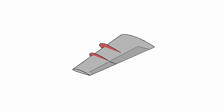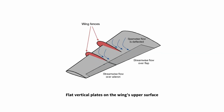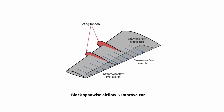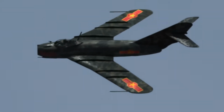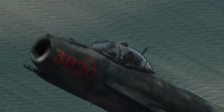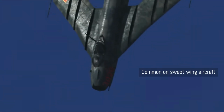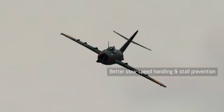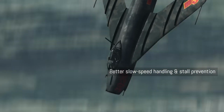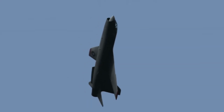Another aerodynamic feature designed to improve performance is the wing fence. These are flat, vertical plates mounted on the upper surface of the wing. Their main role is to block or redirect the spanwise airflow, the movement of air that travels outward along the wing toward the tip. By controlling this airflow, wing fences help prevent the entire wing from stalling at once, especially during high angles of attack. This makes them particularly useful on swept-wing aircraft, where spanwise airflow is more pronounced. The result is better low-speed handling and improved stall characteristics, giving pilots greater control and safety when operating near the limits of the aircraft's performance.